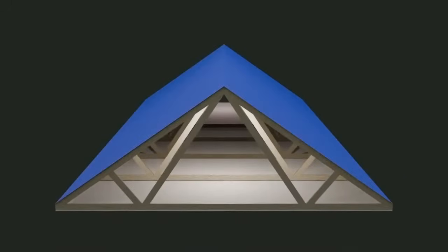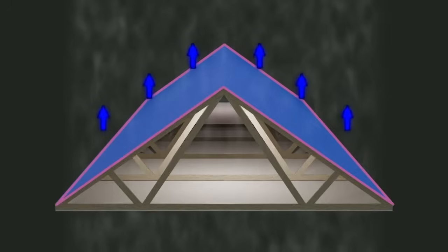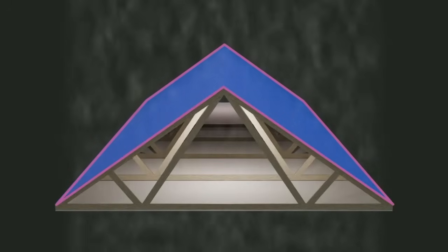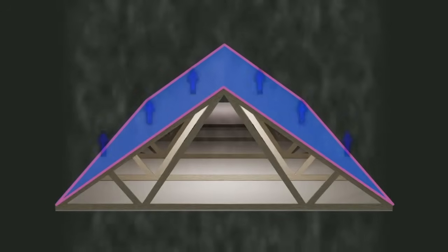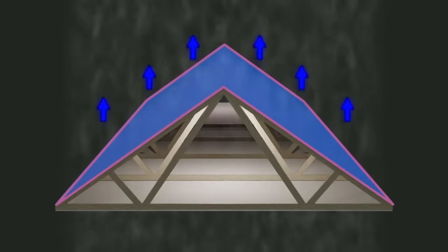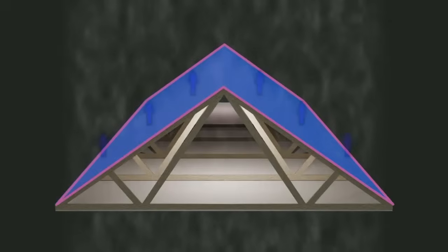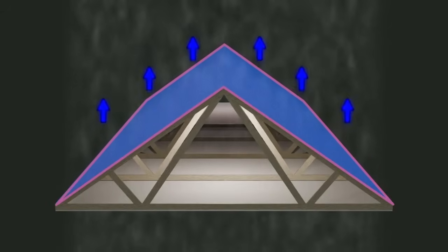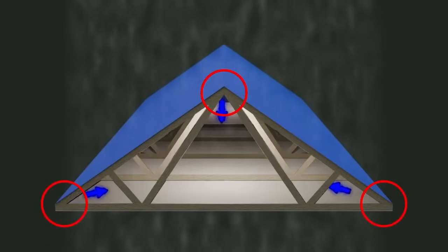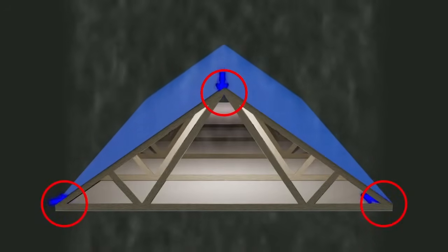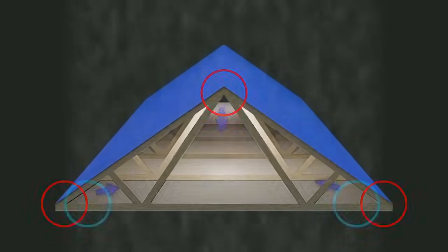What if we could do away with ventilation altogether? This would introduce a number of benefits. Firstly, moisture vapour could escape through the entire surface of the roof rather than specific inlets and outlets. This simplifies the design of complex roof shapes and makes obstructing or inhibiting the flow of moisture out of the roof virtually impossible. Secondly, if there are no openings in the roof, there's no possibility of wind-blown rain or snow entering the roof through poorly designed or installed openings.